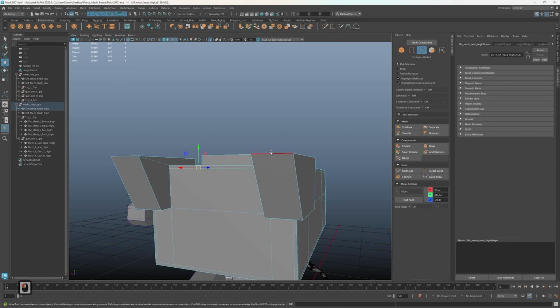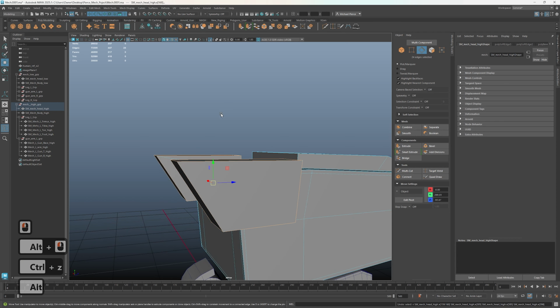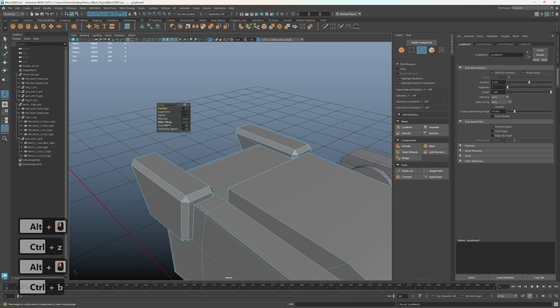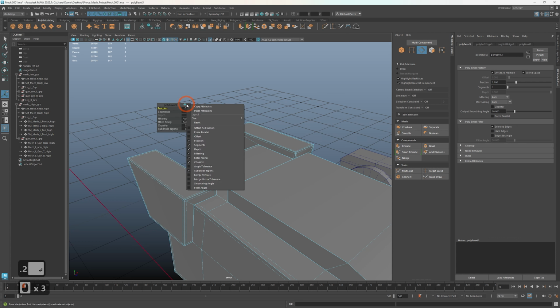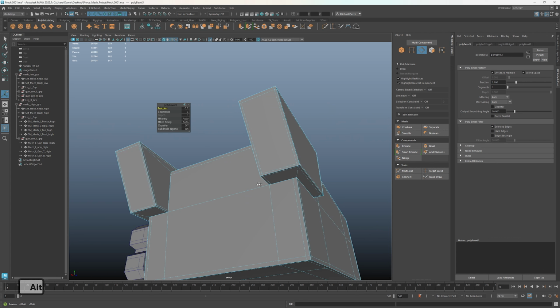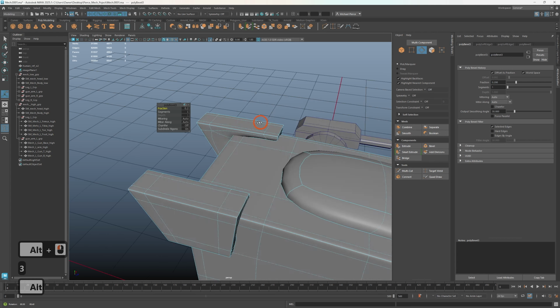There we go. Now that we've got that there, undo, make sure I reselect these guys, bevel them, turn off the chamfer, decrease the fraction down to like 0.2. Holding control will make it a lot faster or a little slower for you, or you can also turn the speed down by clicking on this thing here, the circle, not the 3 dots. Right, and then just going to put it right around here. There we go. But the main thing is, I selected all the edges I needed anyway, so it doesn't really matter.